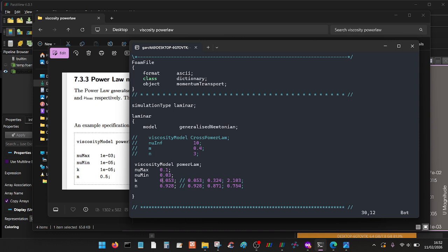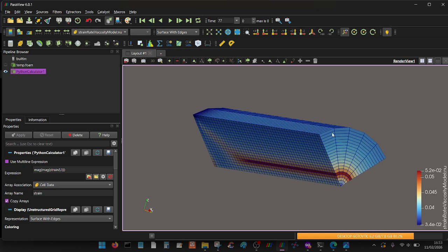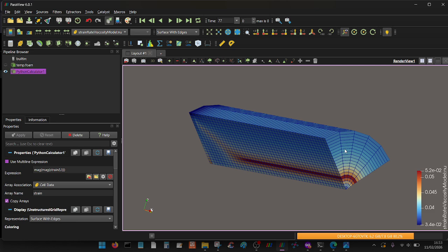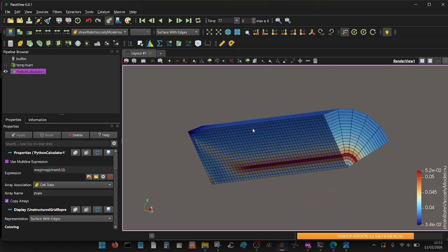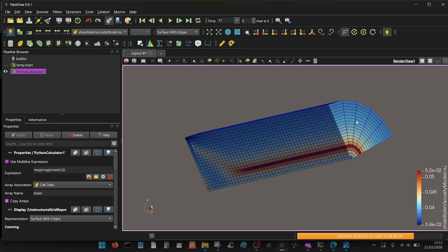And then run it. And when you run it, it runs really quick, like in a few seconds. When you run it, it gives you the viscosity. So in this case, the peak viscosity is towards the center, and then the viscosity is less towards the outside. It'll look different for different power laws or different hydrogels, but in this case we've got that.